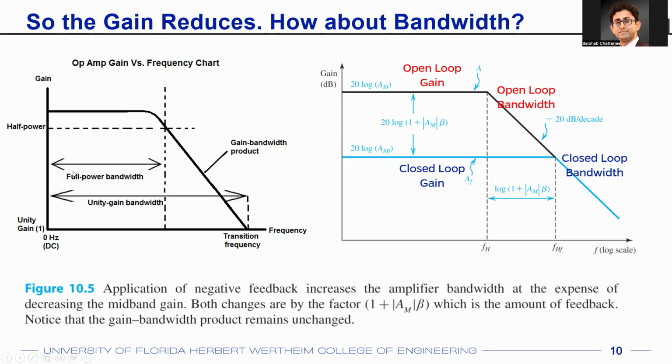Question? Yes. So it's up to a frequency. What does bandwidth mean? Bandwidth means that up to a certain frequency, your circuit works as expected. Right? So your op-amp will not work for infinite frequency. Let's say you have terahertz frequencies and you buy a 50-cent op-amp from the market. That will not work at terahertz frequencies. Probably it will just work at kilohertz frequencies. Right? Bandwidth means at what frequency does it work?